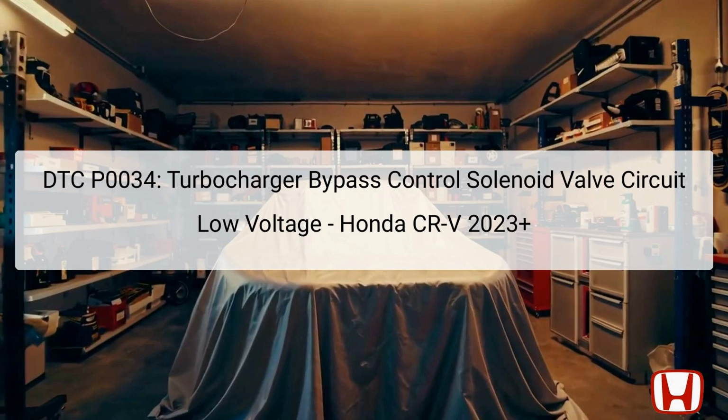The turbocharger bypass control solenoid valve plays a critical role in regulating the turbocharger boost pressure. It directs excess exhaust gases away from the turbocharger when the engine does not require it for maximum efficiency. This valve is typically located near the turbocharger assembly and interacts directly with the vehicle's boosting system. Identifying this error code is vital, as unresolved issues can lead to performance degradation, increased emissions, and potentially engine damage over time.